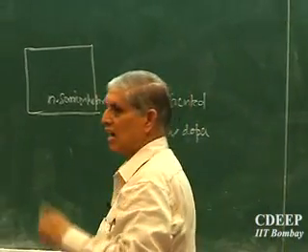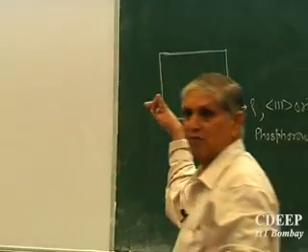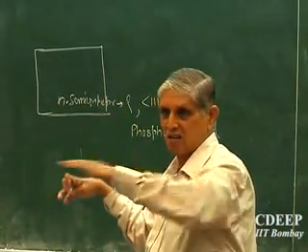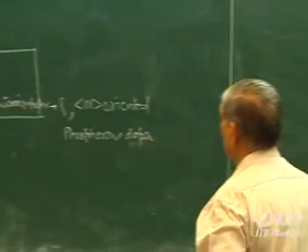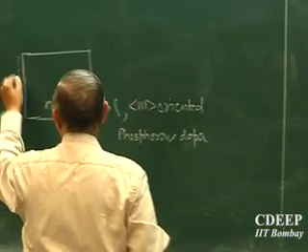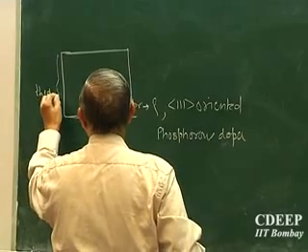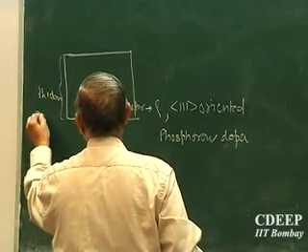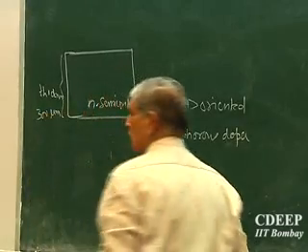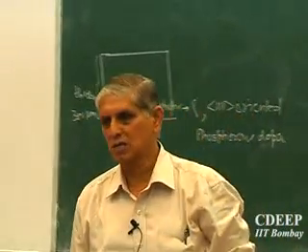The wafers, I have shown you in the first few slides, are circular, these big ones. Nowadays 12-inch wafers are being used; we started with working on 1-inch wafers. So this is only a cross-sectional part of the wafer, seen from across. This is the thickness of the wafer, or rather one chip I am looking at. Typically for 3-inch wafers, this thickness may be around 300 microns. For a 12-inch wafer, it may be around 2 millimeters.